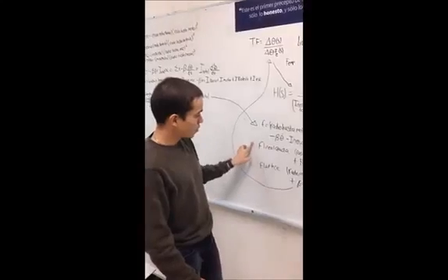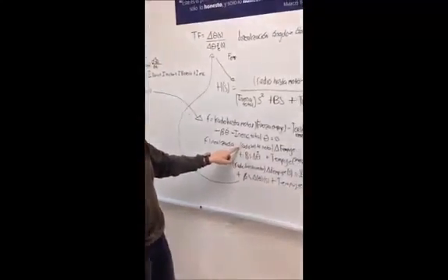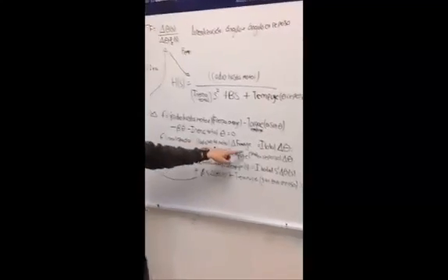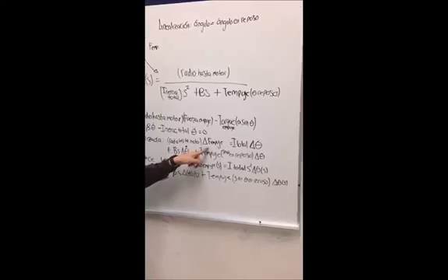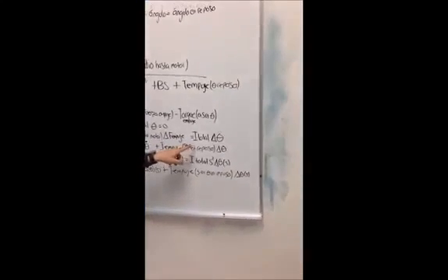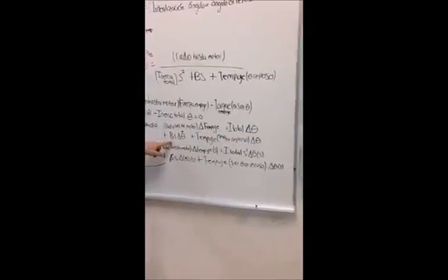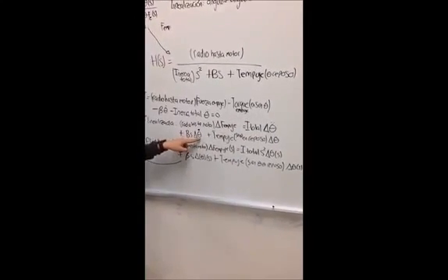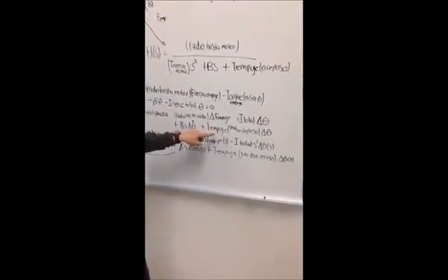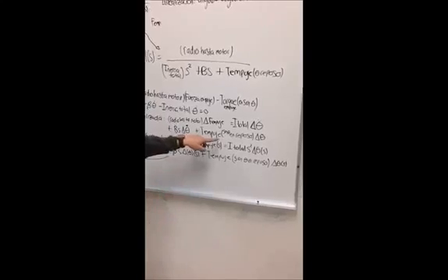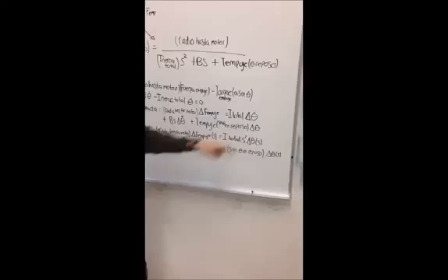So when we linearize the function, it is like this: the radius from the axis to the motor times the variation of the upward force is equal to the total inertia times the angular acceleration plus the coefficient times the variation of the velocity plus the torque of the upward force that I mentioned before, evaluated at the angle of rest, times the variation of the angle.